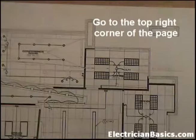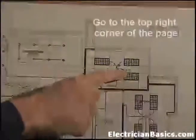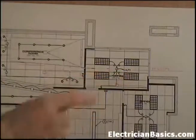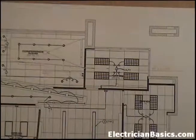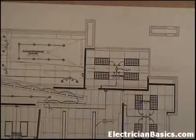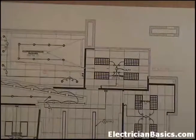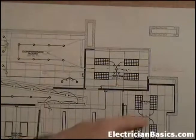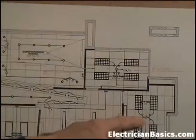Okay, now over here, I want to point out, it says panel E4 circuit 11. And it has its own home run for these lights here. What we did, we said, you know, we have a circuit 9 all the way down at the bottom that's having its own home run. So let's put those in the same conduit, because circuit 9 comes all the way up to here for its last junction box for its lights.